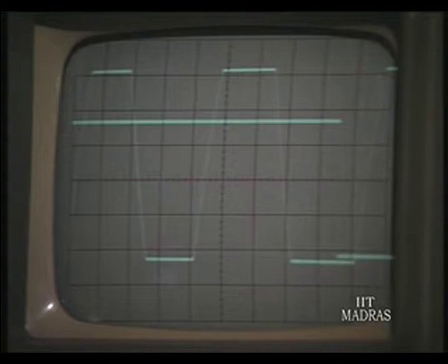Slowly, if you do, or adjust the free running frequency slightly. No, it is not. In lock, it is absolutely stable. There you are. So, this is subharmonic locking. And again, slowly change the incoming frequency. See, it is maintaining itself under lock beautifully.